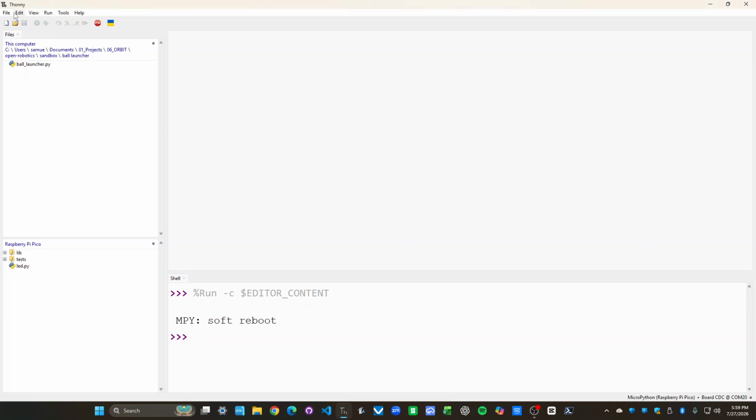So as I said, first I've got to do File, New, and here's my new file. And I'm going to remember imports come first. From machine import Pin, because this library has things like Pin, which actually allows us to program pins. Make sure, by the way, that the capitalization is exactly this way. Like most programming languages, Python is sensitive to capitals. If you capitalize it, it does not know what you're talking about.